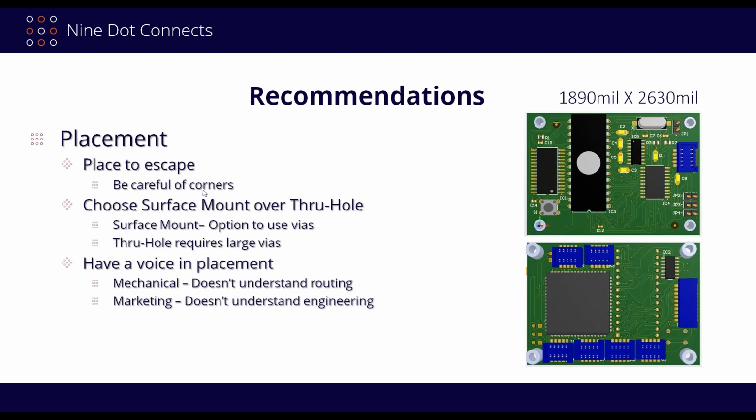So I'm really cutting my escape routes here, and that's why you want to be very careful of putting things into the corners, especially things like BGAs. You want to choose surface mount over through hole. That's what we found here.